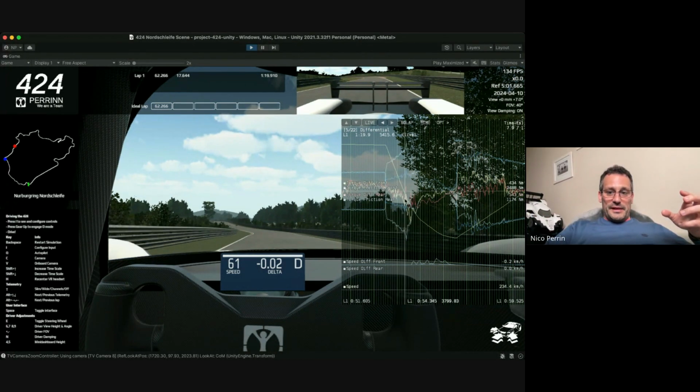And you can see it's building up to the point, the yellow trace here, where the friction in the diff is opening, and we cannot transmit that torque across the diff anymore. And you see that it's basically meeting that curve, the blue one. That blue curve is how much torque could be maximum transmitted across the diff. So the yellow one is the actual torque. The blue one is how much maximum you could transmit. When they meet, basically, the diff starts to slide. It's like a clutch.